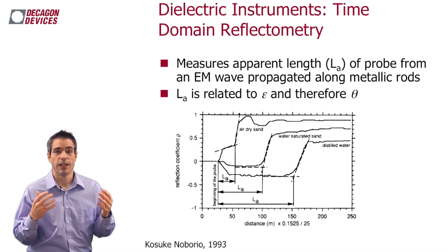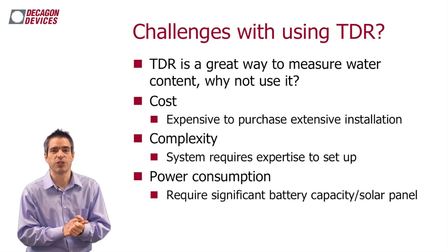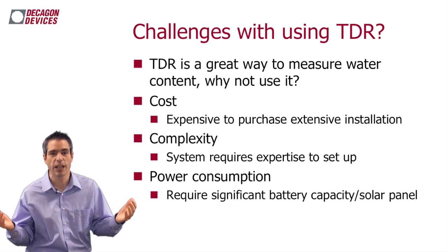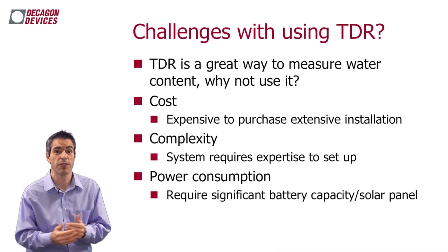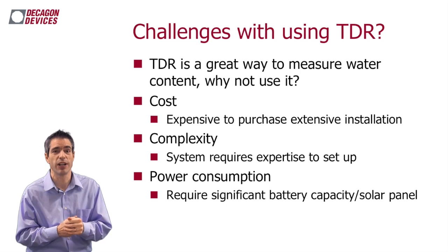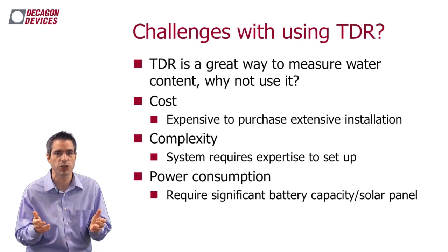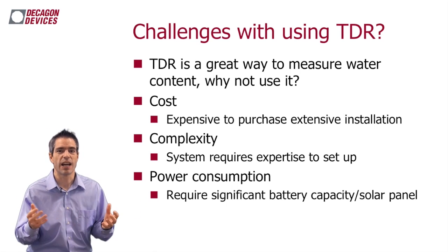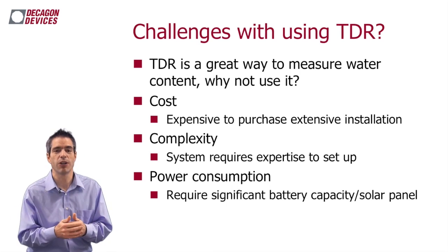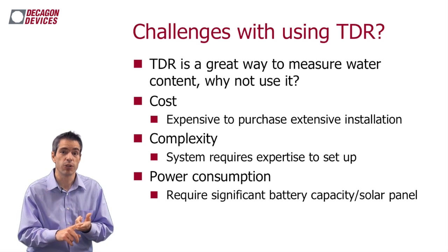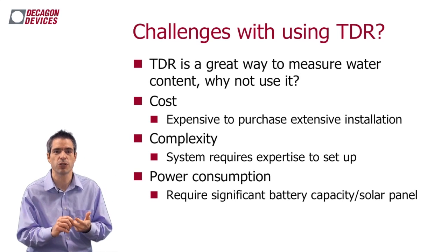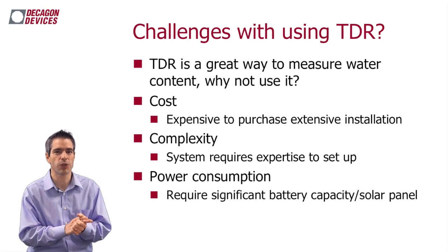Now, what are some of the challenges to TDR? Well, TDR is actually a great way to measure water content. Why can't we use it everywhere? It actually does work very, very well. It suffers in the high clays. That's been well documented more recently in literature. There was a feeling at one time that it works in every soil anywhere, but we really know that is not true. There are some areas where we need to do another calibration, but with a better calibration and better analysis techniques, especially those starting to appear in the literature now, we can get good values out of this measurement, even in those difficult conditions.